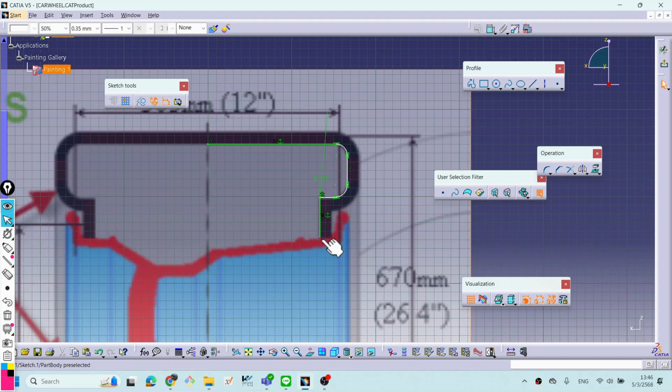If you need to create the solid in the part design module in the command pad, you must have the closed profile in the sketch before. Otherwise, you could not create a 3D part, right? Okay, it's the pop up, right?